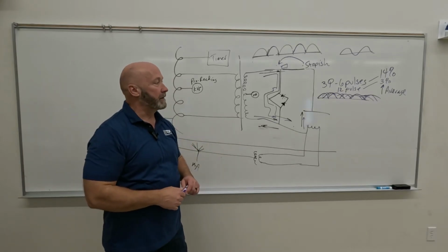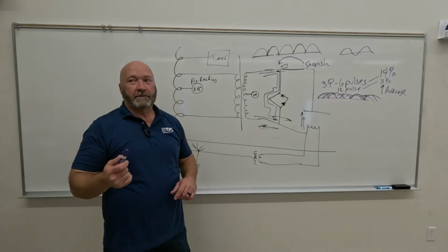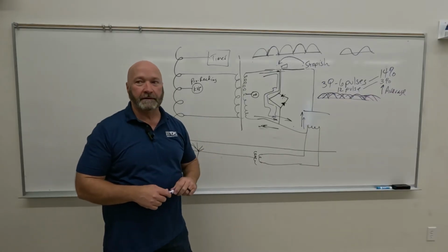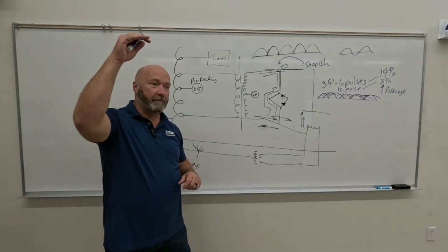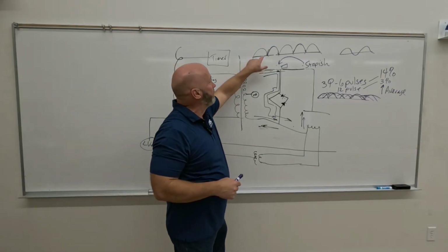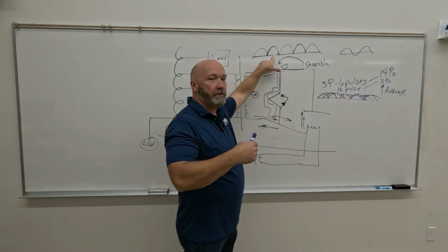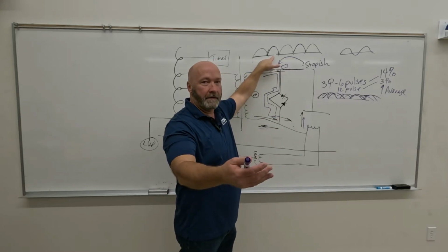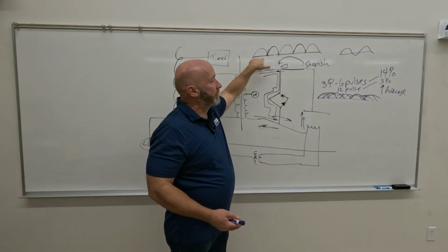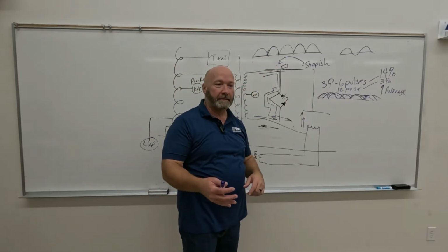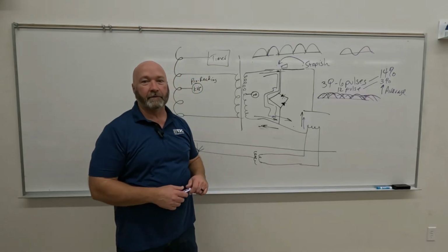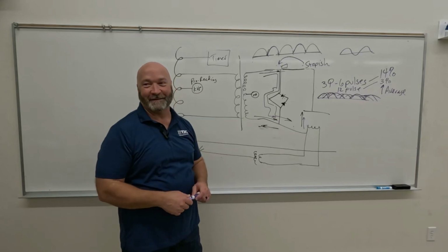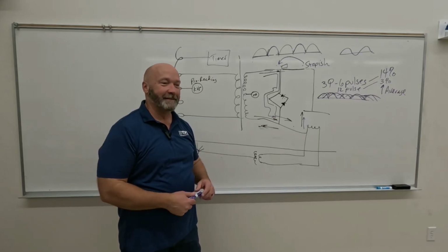Yeah. Okay. So now here's the other part that doesn't make any sense. So we go from single phase to three phase. We're going to get a higher average, but when we went from unrectified to rectified, we also got a higher output, meaning mass essentially, right? So we go from single phase to three phase, you would expect that our output would increase by a factor of? Yeah, you would think so. It doesn't. It's a factor of 2.